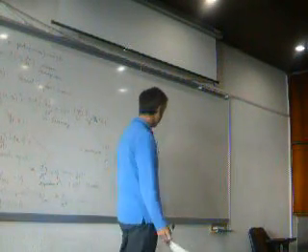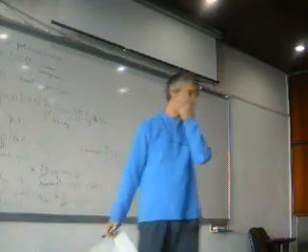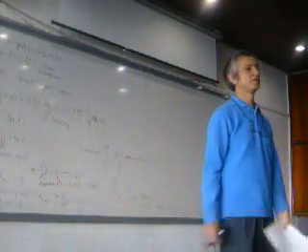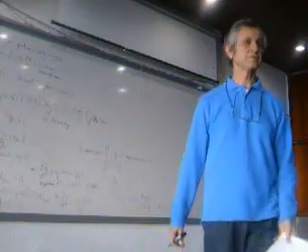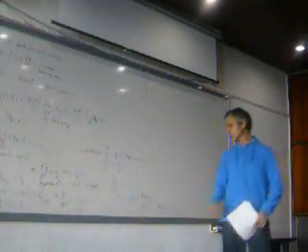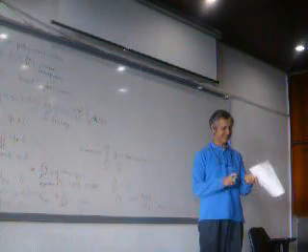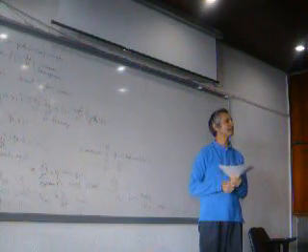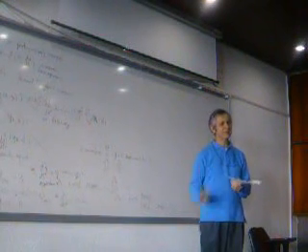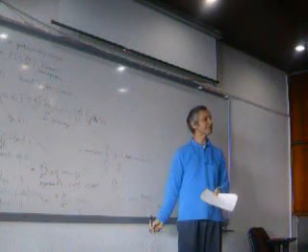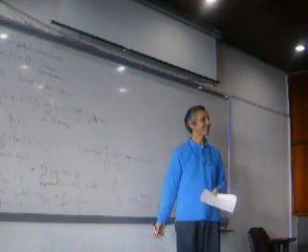Now, borderline stable means that it's not asymptotically stable. It's not asymptotically approaching the equilibrium, but it's nevertheless stable. That's borderline stable. Make a little note here. The borderline stable result, you can guess, it's not hard to guess this. It's not 100% reliable. Why? Because you linearized it already and you obtained borderline stable. Now you are suspicious. Why?